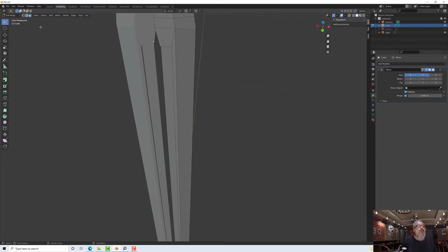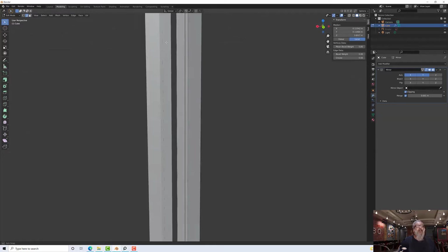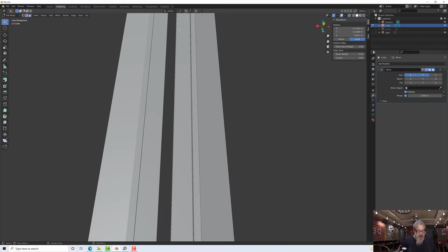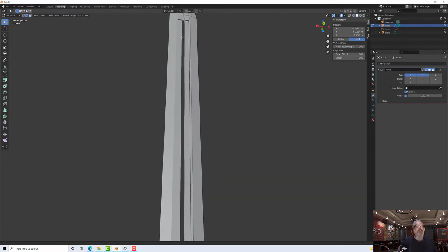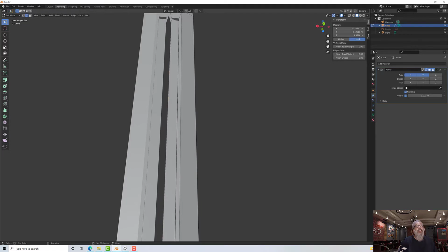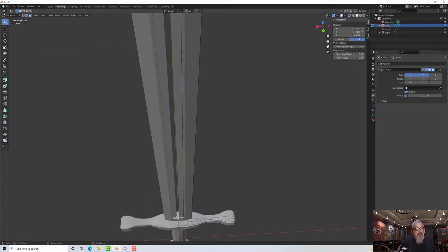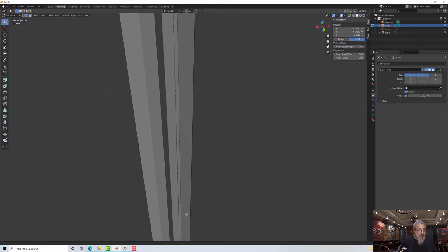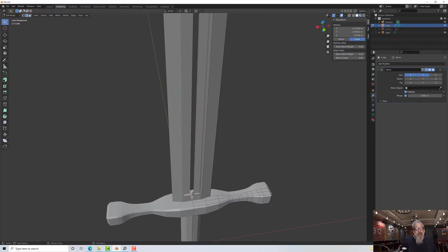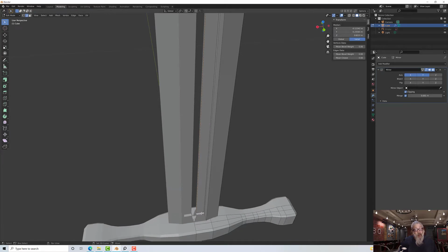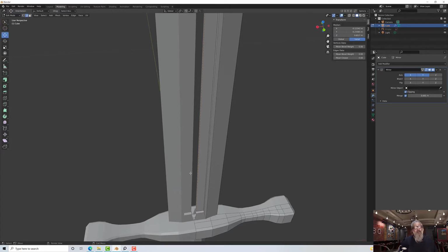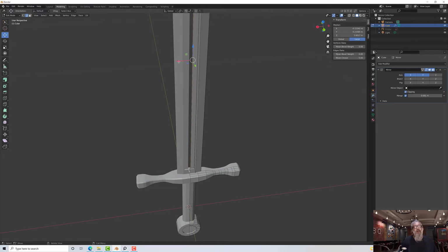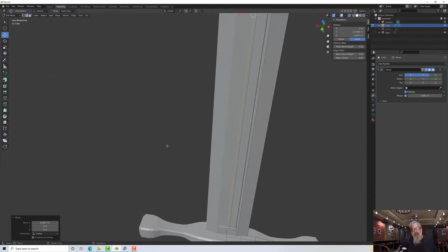So if I go to my edge there, select that edge, I need to select the top edge. Let's press the period to focus. I need to select that edge as well, and I should have one down the bottom too. It's getting awkward. There it is. So that one as well, and then when I press G to move it, if I move it beyond the center it just stops, and that's what clipping does for you. So what it's doing is just closing off that face.